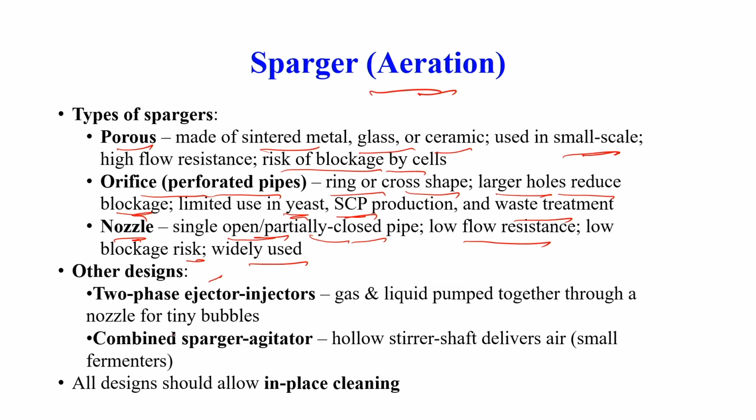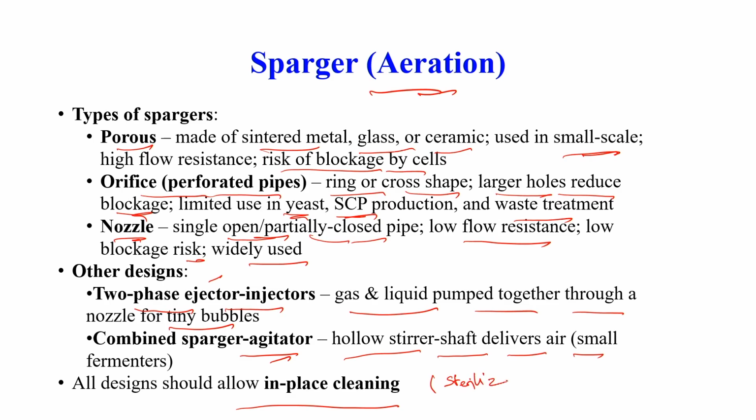There can be other designs, as I told, such as the two phase ejector injector, where gas and liquid are pumped together through a nozzle in order to generate tiny bubbles, and the combined sparger agitator, like a hollow stirrer shaft, delivers air. It is very important that all designs should allow for in place cleaning, meaning in place sterilization, to avoid contamination in the bioreactor.